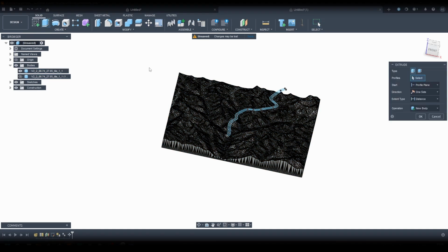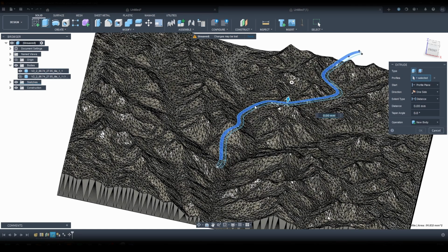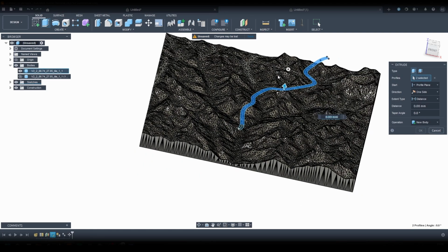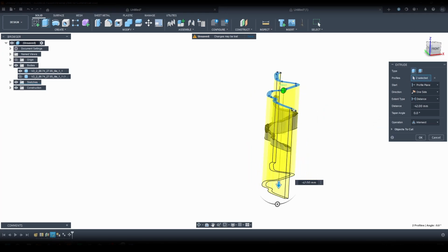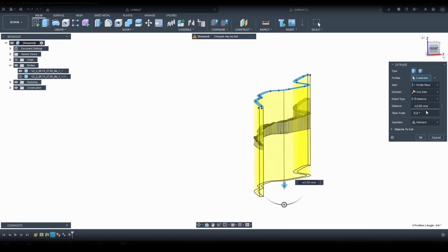We're going to unselect the view for one, and we're going to extrude the path now into the first one all the way through, and on the operation is going to be an intersect. So that's our intersection path, and hit OK.